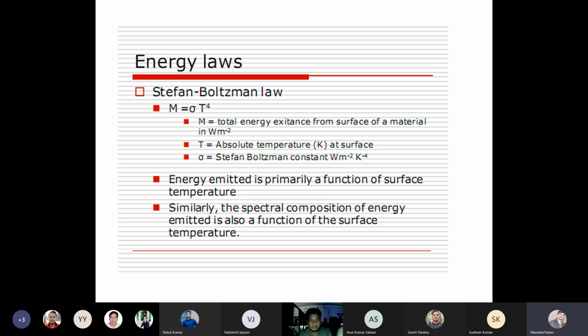If we see the backward flow of this color assignment, from the color assignment towards the energy coming from a particular grid: light color, high DN number, high energy content, high reflectance from the material in that particular wavelength. For the dark color, low DN number, low energy content, low reflectance from the material. So there is a direct relationship.